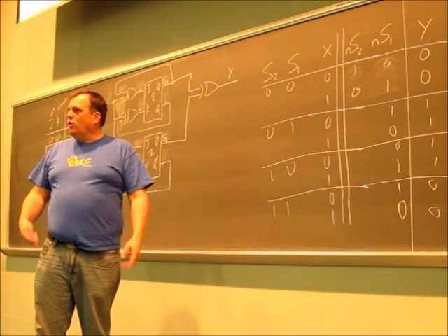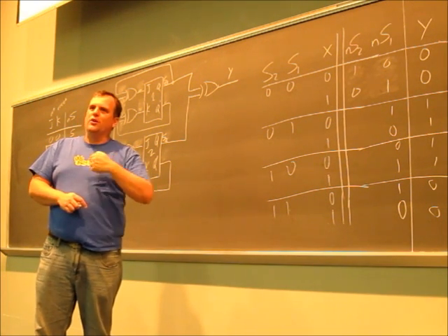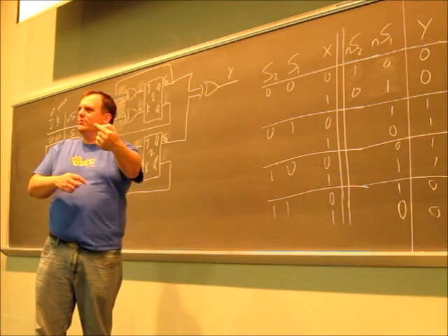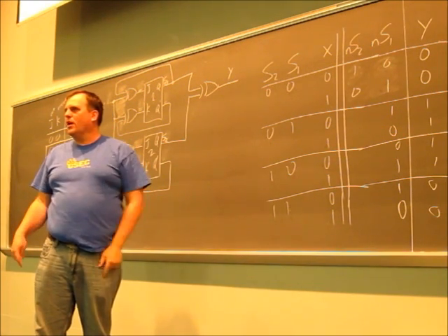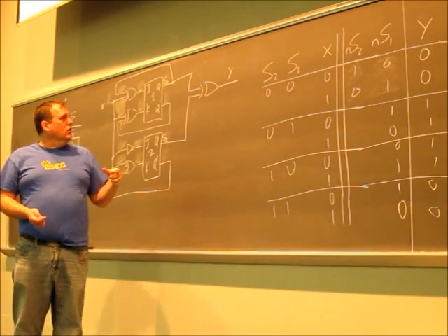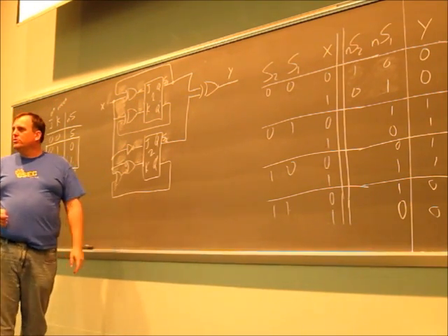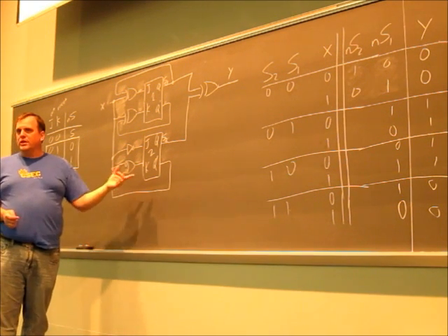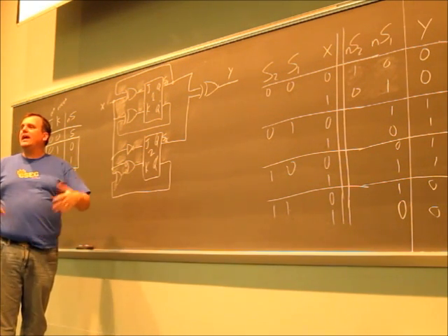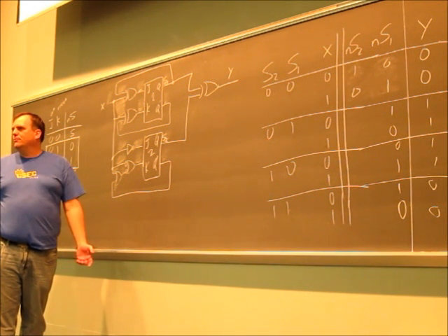So all I have to do is decide which wire I run out. If I run out the wire from one side, I get Q, I run out the other one, I get Q prime. I run them both out, I get both Q and Q prime. So if I'm going to use Q and Q prime, which in this case I was going to use, it's easier to run them out from the actual circuit than put in an extra inverter to make a signal I already have.